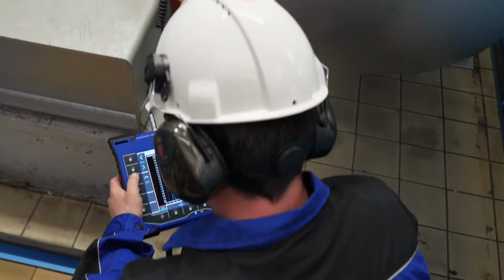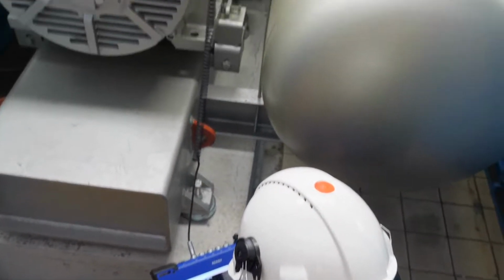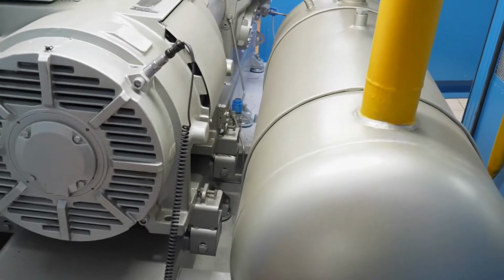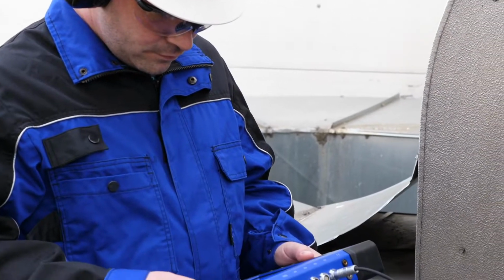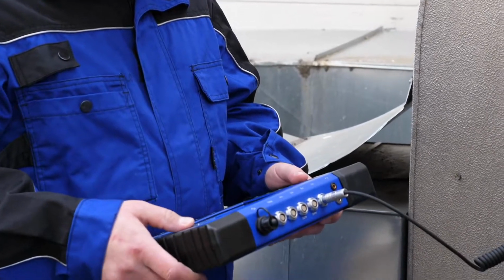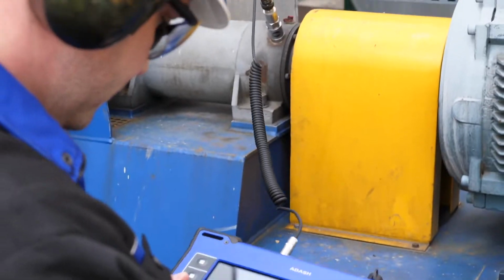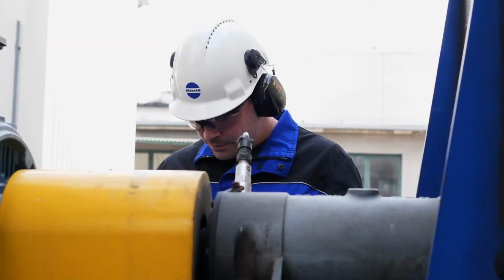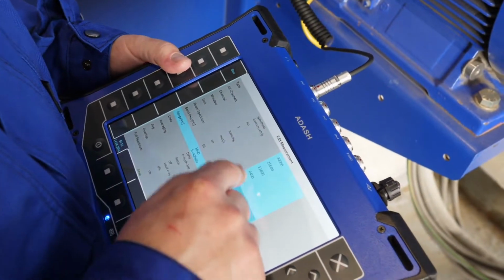Predictive maintenance, and particularly vibration measurement, is one of the best and most proven methods for knowing the actual condition of your machinery. It allows you to track its condition over time and enables you to plan and schedule potential repairs of the machine. However, it can never work 100%, and some sudden machinery breakdowns can still occur.